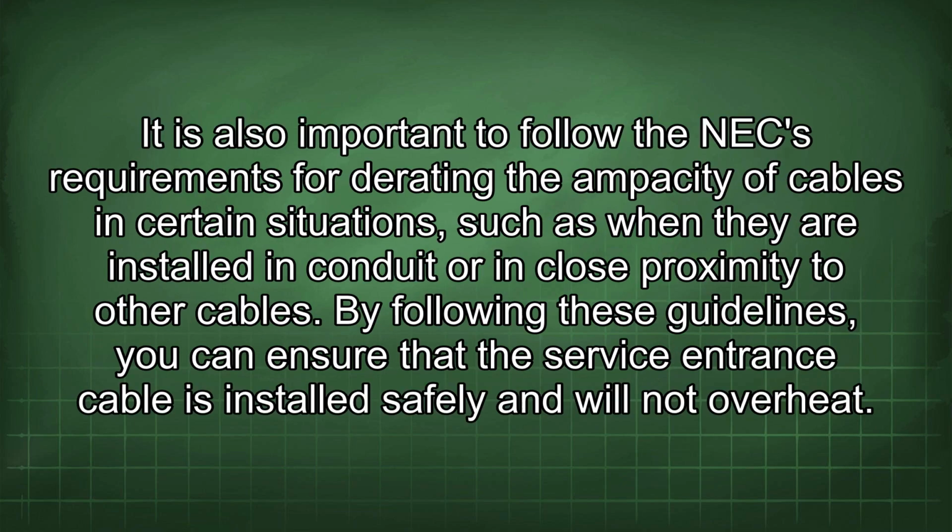It is also important to follow the NEC requirements for determining the ampacity of cables in certain situations, such as when they are installed in conduit or in close proximity to other cables. By following these guidelines, you can ensure that the service entrance cable is installed safely and will not overheat.